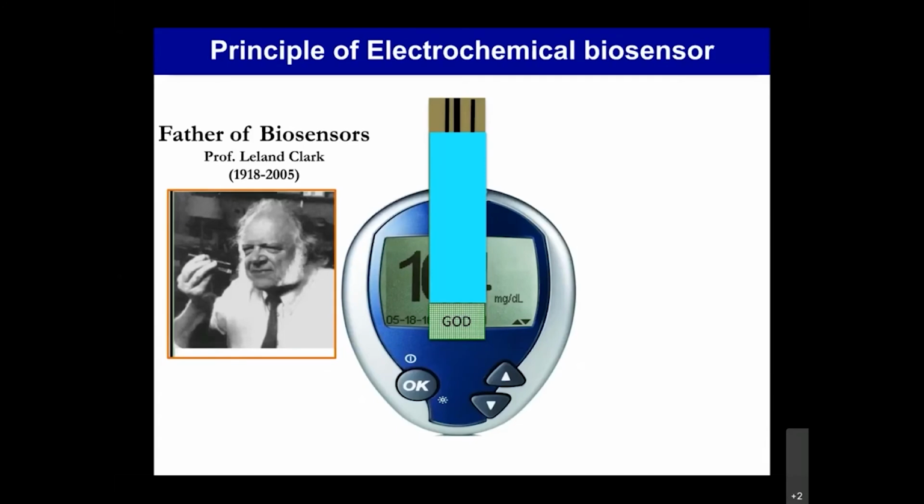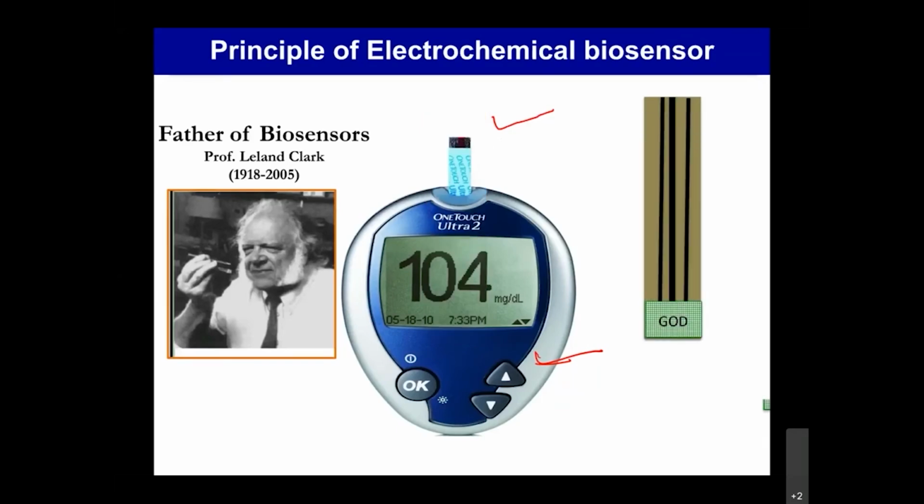The glucometer has two components. One of them is a reader, which is an electronic meter, and the other component is the test strip. It is the test strip which is the key, and which is going to do the magic in terms of testing. If you look at this test strip, what you see here is something called an electrochemical cell. This is essentially printed carbon-based electrodes. These are long lines which take the signal from the electrochemical cell onto the reader.